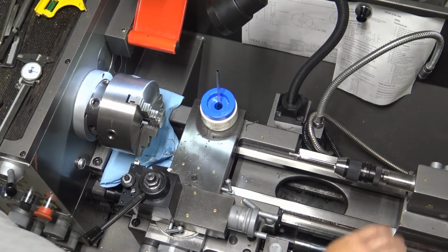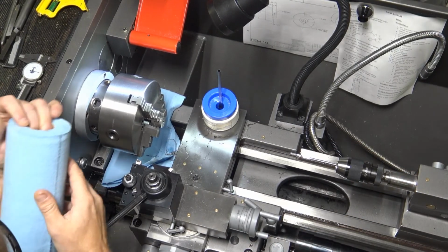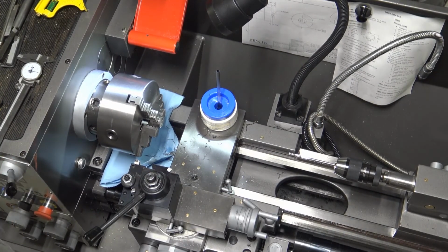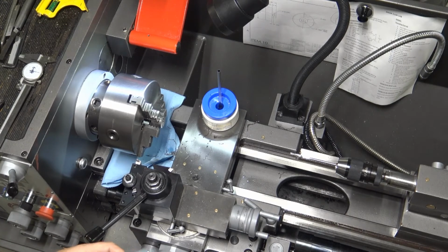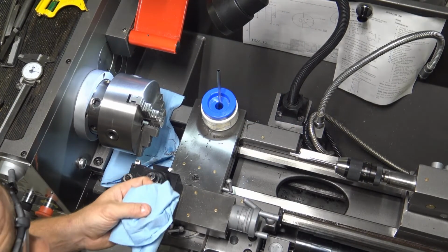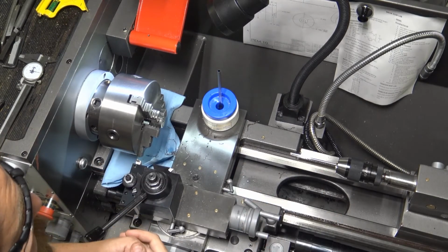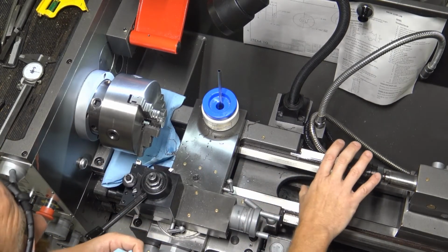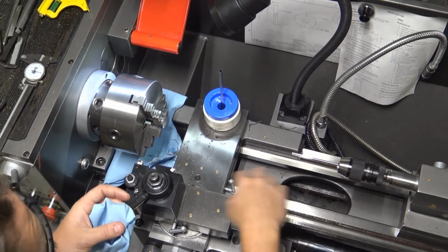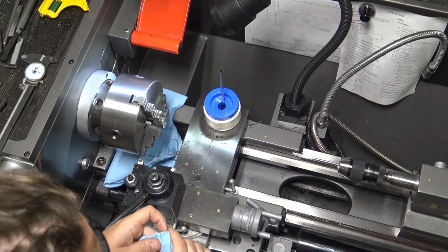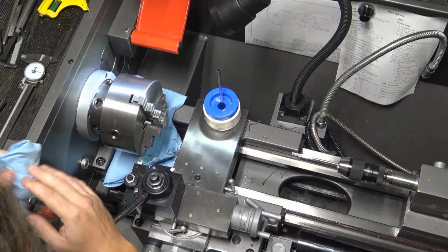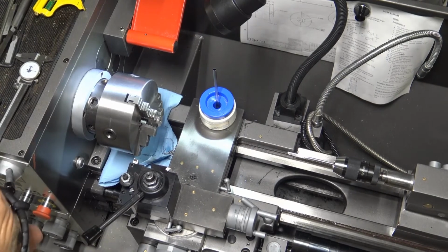So I will wipe this reamer off, and normally we always want to take the tools out of the tool chuck when we're done using them, because of safety concerns of cutting yourself on drills and whatever else you put in here. But we're going to need this setup for when we flip the part over. But before I flip the part over, I want to just quick deburr it.